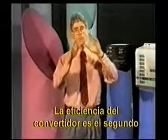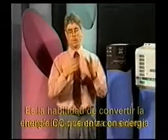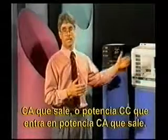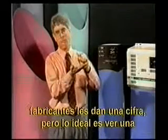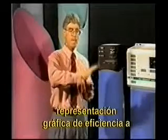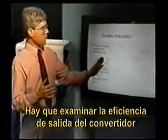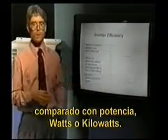The second important factor that we need to consider with inverters is their efficiency, their ability to convert DC energy in into AC energy out, or DC power in into AC power out. Again, many manufacturers will give you one number. What you typically would like to look at, though, is a graphical representation of efficiency over different load levels. What you want to do is examine the output efficiency of an inverter compared to power, watts or kilowatts.